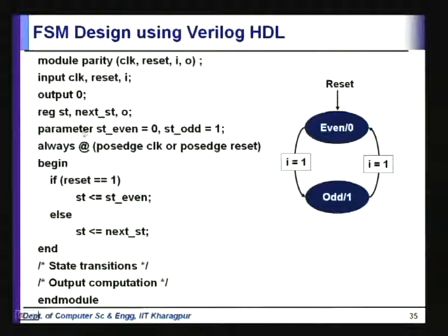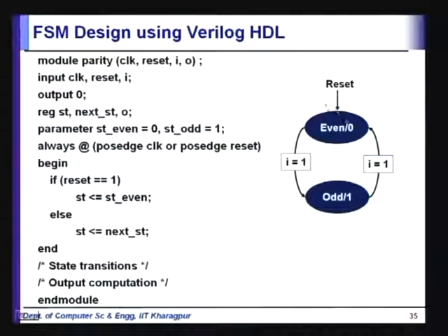We are using some registers internally for maintaining the state of the system. We need the state. Why? Because we need to know what is the current parity, and if the current parity is even and you get another one, then the parity becomes odd, and then it remains odd until you get another one. So this is a finite state machine which describes the behavior.